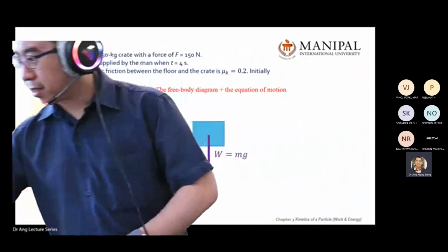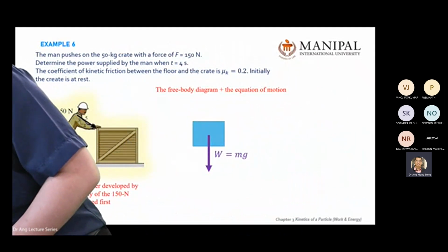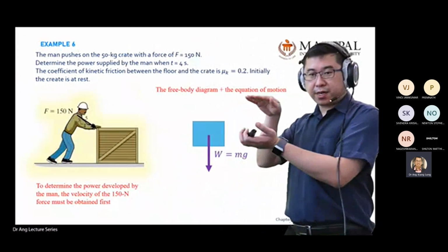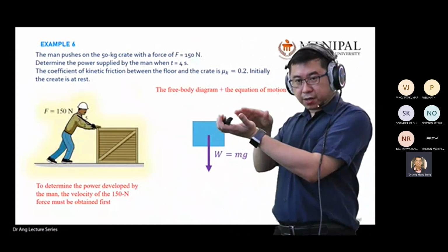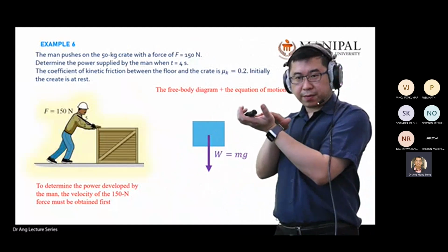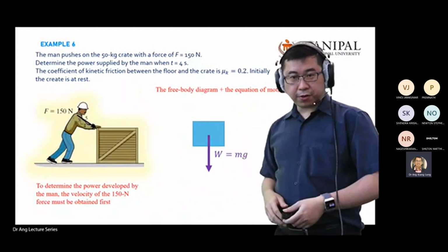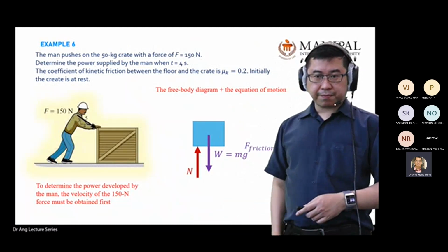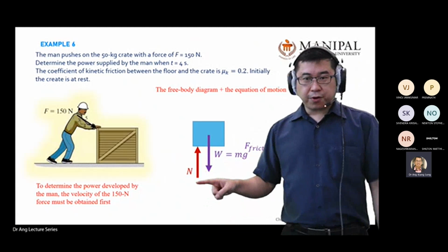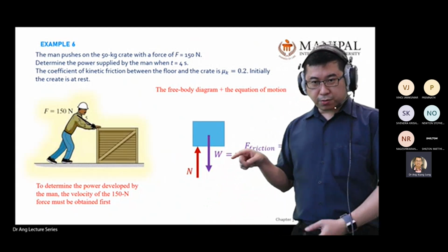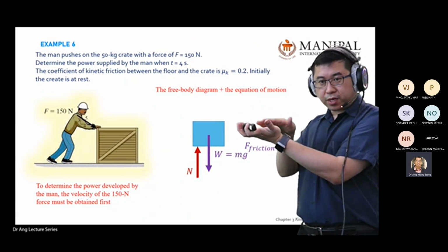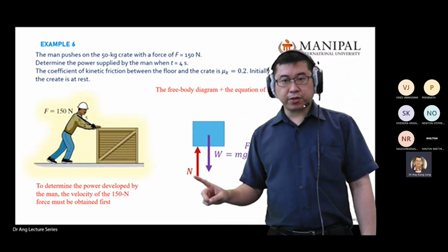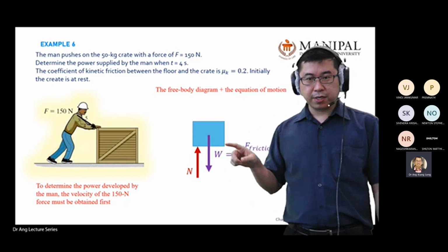So when you have contact, you have a normal force. Okay, so when you have an object on a surface, you have a normal force. So later you'll see the normal force over here. All right. This normal force is automatic when there's contact between the object and the surface. This normal force is going to help you to find the friction force.